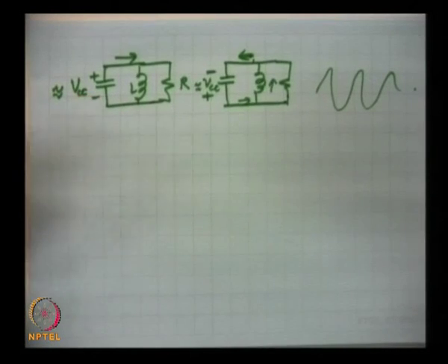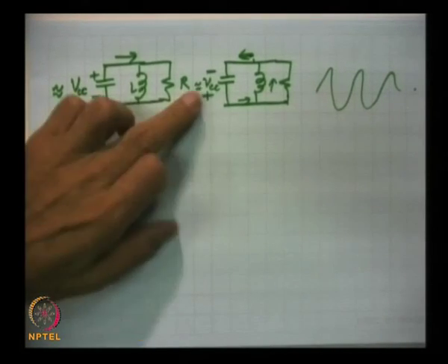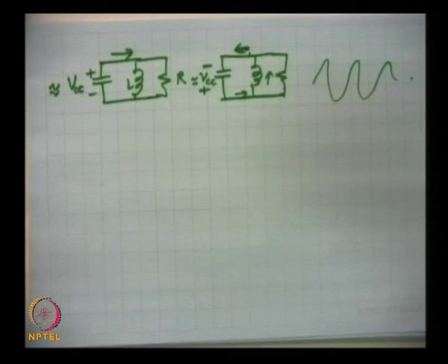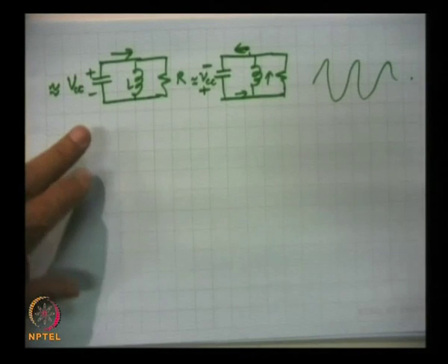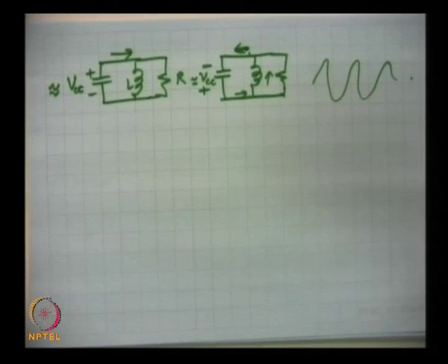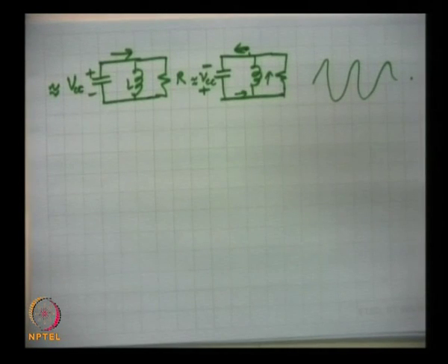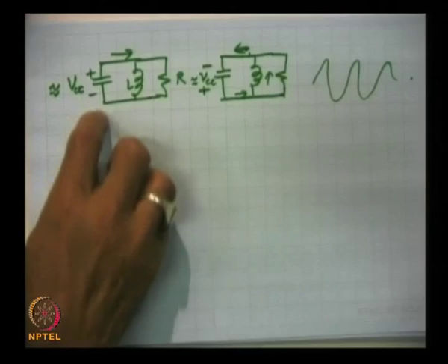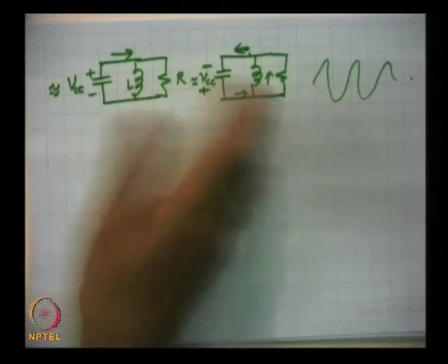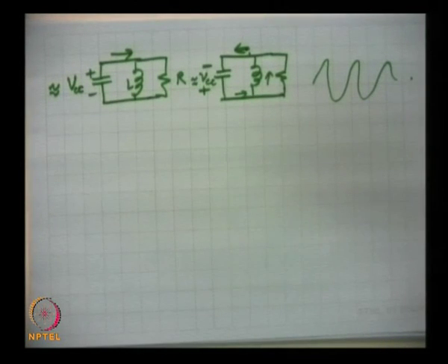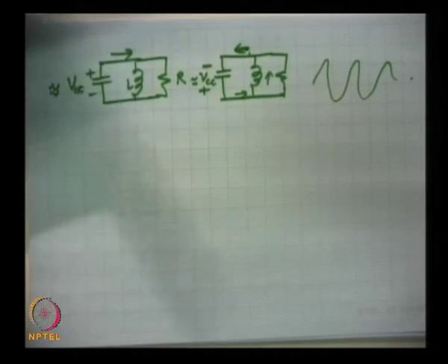That is why I said that this will be charged close to VCC, and here it will fall further, but the fall is only a few percent of the original VCC value. So, this is still close to VCC. By then another clock pulse will come and charge it again to the same voltage, and the process will repeat. This way we continuously get an output pulse.